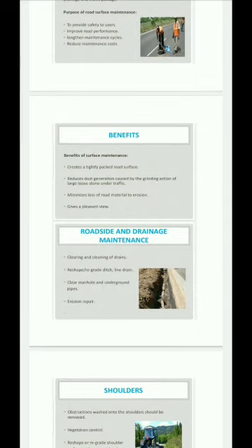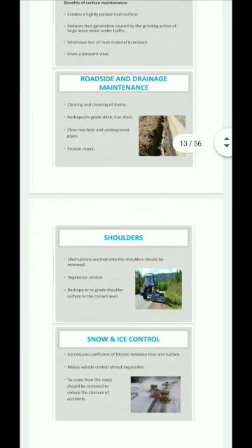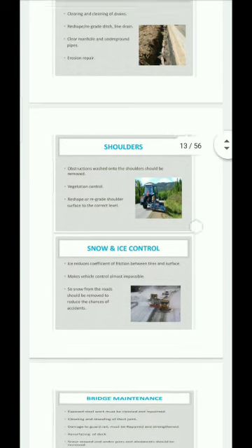Next, roadside and drainage maintenance. Clearing and cleaning of drains, reshape and regrade ditches or line drains, clear manholes and underground pipes, erosion repair. Shoulders: obstructions washed into the shoulder should be removed. Vegetation control, reshape or regrade shoulder surfaces to the correct level.